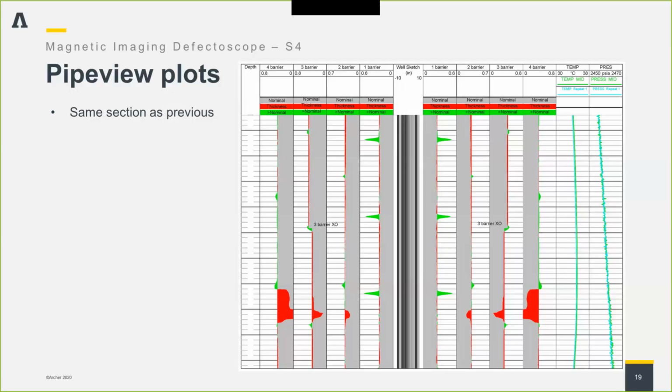If it's on an exterior string, it's very likely to be corrosion rather than erosion, unless you've got a lot of cross flow going on. But to answer the question in a roundabout way, the tool does not discriminate between what might be inside or outside. What it does is give you an average thickness.